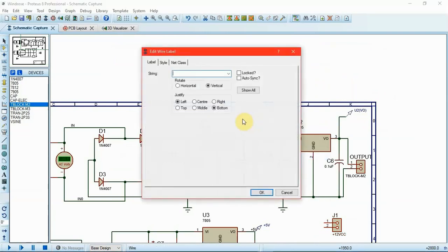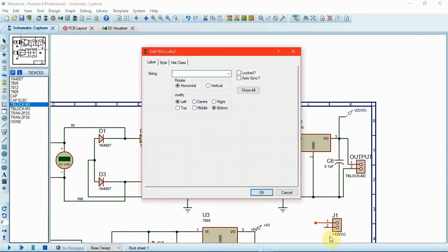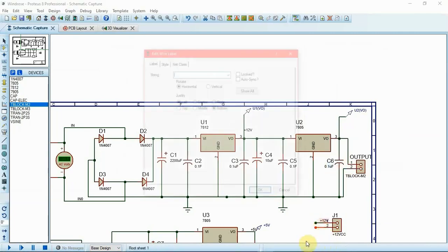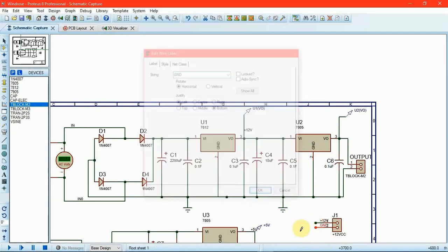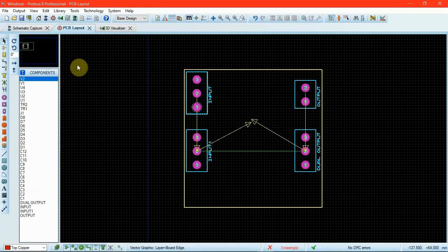If we name two wires with the same label, it tells the software that these two wires are connected. We must remember that even the caps lock plays a vital role in naming the wires. So here we place the wire label for ground as well to show that this wire is connected to ground, and the connection for the T block is done.